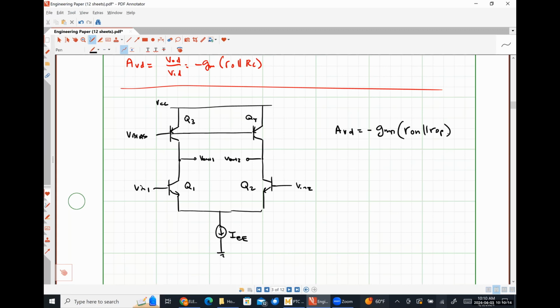If we wanted to get crazy, we could actually replace transistor Q1 with a cascode amplifier instead. We would need to replace transistor Q3 with a cascode current source, but we would still have a differential pair. Its gain would be incredibly large because the cascode's gain is so much larger than just the common emitter.